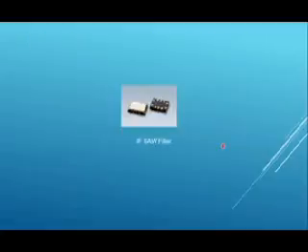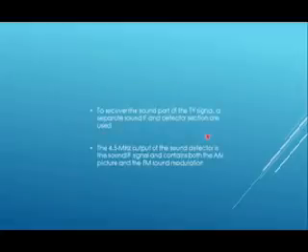The SAW filter greatly attenuates the sound IF to prevent it from getting into the video circuit. The IF signals are amplified by IC amplifiers. The video luminance signal is recovered by an AM demodulator. To recover the sound part of the TV signal, separate sound IF and detector sections are used. The 4.5 MHz output of the sound detector is the sound IF signal and contains both the AM picture and